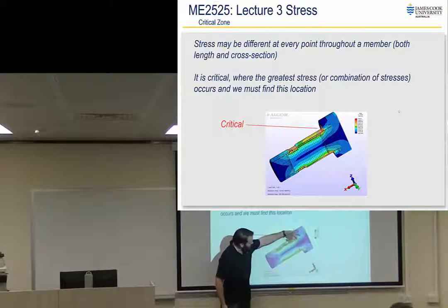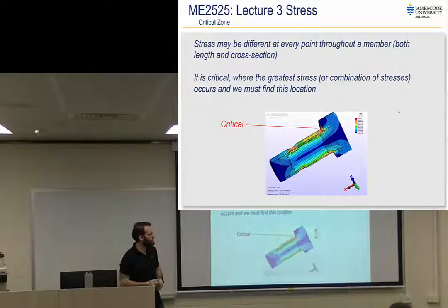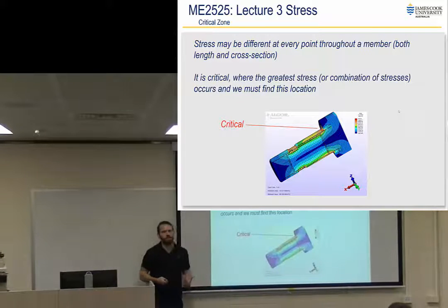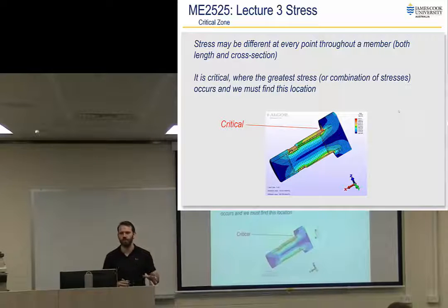And so that might, as it rotates, cause a crack to come in here, and then the large roller to actually shear off. All right. And so understanding where that critical zone is, FEA is very good for complex stuff, but we're going to be able to do that for the more simple shafts, beams, bars, that kind of stuff. The bread and butter things, bolts, welds, gears, all of that sort of stuff, we can analyse by hand, and we have a good understanding of where the critical zone is actually going to occur.